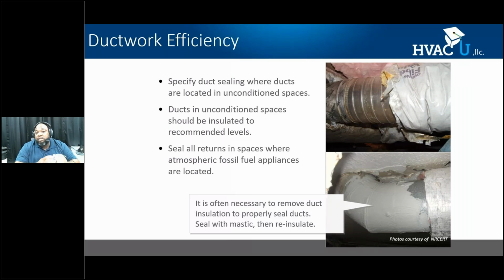Don't arbitrarily seal ducts unless you truly understand the airflow and static pressure of that system, because you will find cracked heat exchangers, burned out ECM motors. You'll find all these negative consequences as equipment damage because we improperly sealed the duct system. But properly sized ducts should be sealed. Properly sized ducts also should be insulated if they're in an unconditioned space.